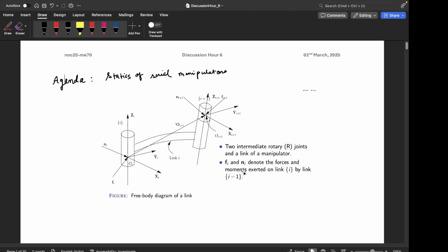One is to directly take derivatives of the forward kinematics equation, and in another approach, we used velocity propagation, both linear velocity and angular velocity propagation, to find the expression for the end effector velocity in terms of the link lengths and the joint velocities. And then we basically concluded that we get the same matrix in both the cases.